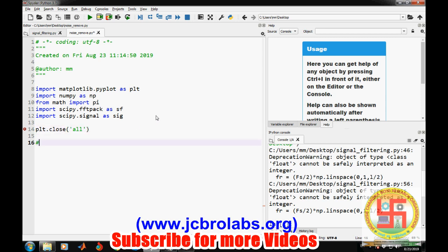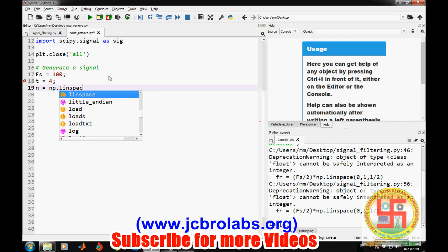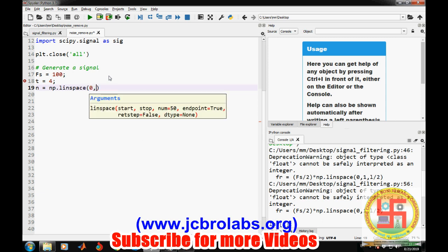Now first we will define a signal. We will simulate a signal in order to demonstrate it. So, generate a signal. As we know, when generating a digital signal, one of the important features is the sampling frequency. So first we'll define the sampling frequency of our signal, which is 100 Hertz, and then we'll define the time duration for which we want to generate our signal. So let's say 4 seconds, and then we will generate the samples. For generating the samples, we have np.linspace from 0 to t at the interval of the sampling interval, so 1 by fs.